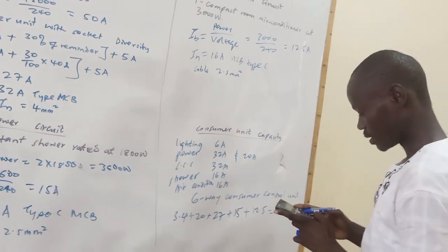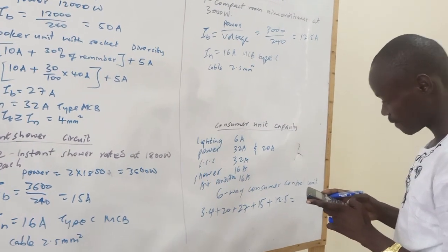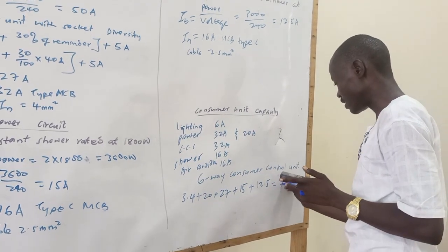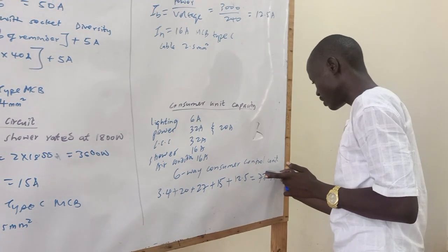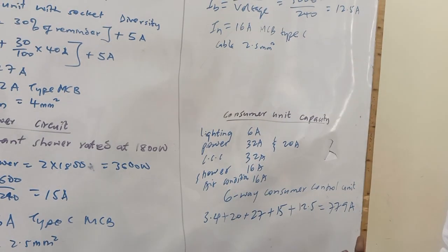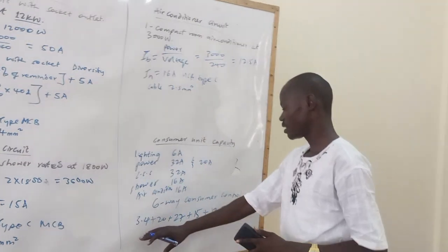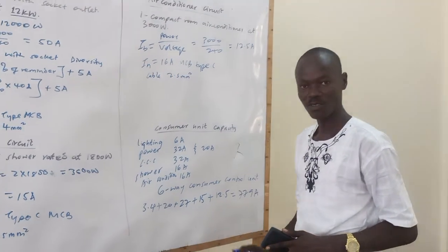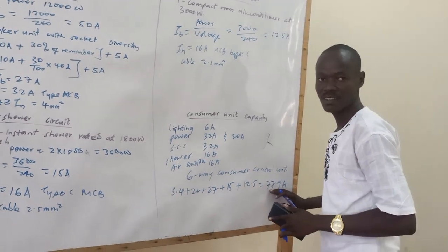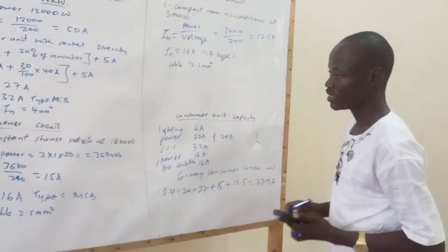So I'm getting 77.9 ampere. So you can see. So in this case, you're not going to support. In most cases, people just use 63 amperes as the double pole circuit breaker for this case. But this one, you see, the total design current exceeds 63. So you can go ahead and use 80, or even use 100 for effectiveness. So if you're using 100, it means that everything will be supplied with it.